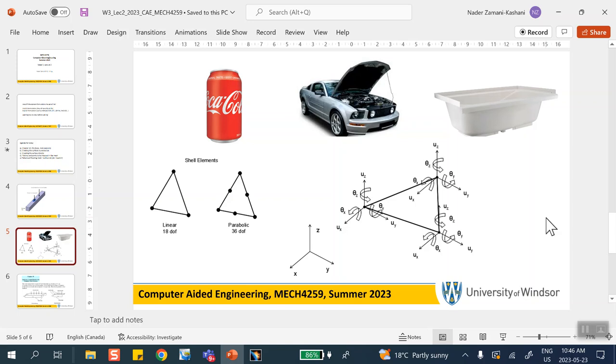So obviously something gives in. It's just like beams. Beams are efficient elements for certain problems, but not every problem can be done with beams. And also something gives in. In other words, the results of a beam are not as accurate as doing it with a fine enough, good three-dimensional mesh. The same thing is true here. If you can model your problem in 3D with a good mesh, it will give you better results than a shell. However, it may not be economically possible to do that.